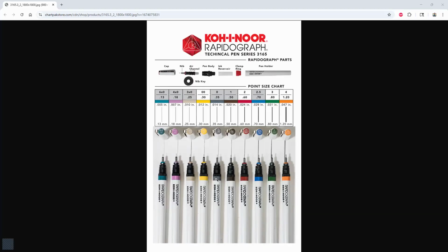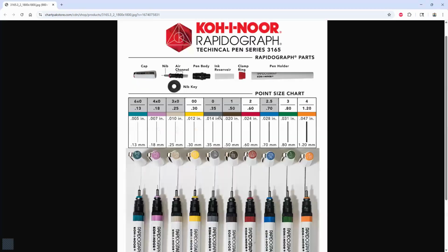And then the gray also was relatively common. And then when we were going to draw walls, if we were doing a floor plan, we would always go over here to either the brown or the red. And a few times you would end up using this orange one, which is a 1.2 when we were putting down lines that were meant to represent the ground if we were doing elevations. But this is where it's tied into. This is where AutoCAD got the idea, where color coding equals a specific line weight. And it's all set to millimeter. We're just used to that. But there is a way to switch it over to inches, but not too many people will do that. So if I can zoom in here, yeah, it does let me zoom in a little bit there.